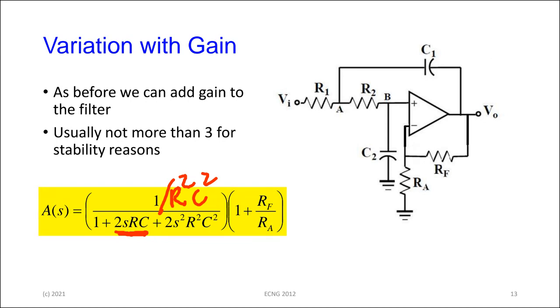So the normal rule of thumb is that usually you would not put too much gain on this particular amplifier here. If you really want to have some gain, then you run it to a second amplifier somewhere and let that do it. But the particular active filter itself, you try to keep the gain relatively small, and it's usually just to compensate for the losses of the passive part of the network. Yeah? So just a comment, but yes, you can put gain in it, and it's something that can be easily simulated just to see the behavior.